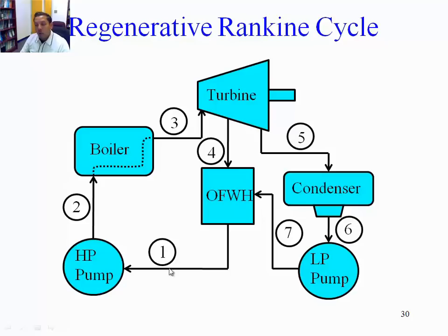Now, what we want is that point 1 to be a little hotter than before. And in order to do so, we are going to mix it up in an open feed water heater with some of the water that comes out of the turbine at an intermediate stage.